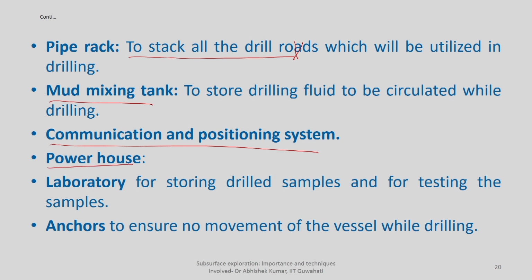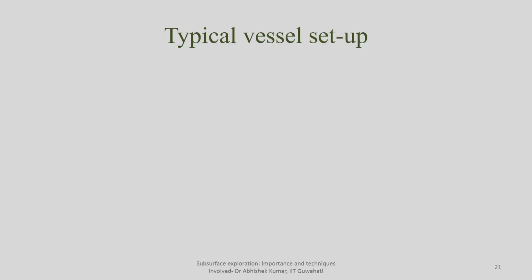Then the powerhouse, because you must have a continuous supply of power in order to do the test. Then a detailed laboratory, where you can test the samples you have collected and also store samples collected from different depths, again in situ at the vessel itself. Then anchors, to ensure no relative movement of the vessel, particularly while drilling. Otherwise there will be breakage or failure of your drilling assembly as well. So, this is a typical setup.